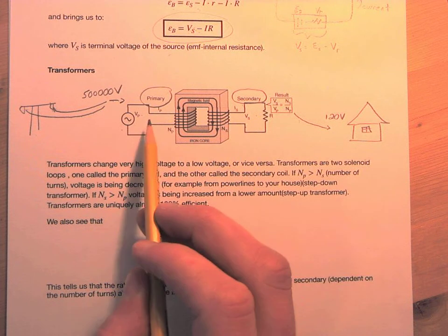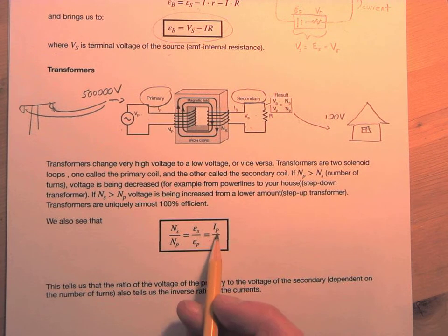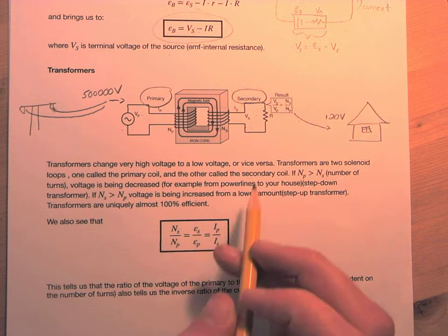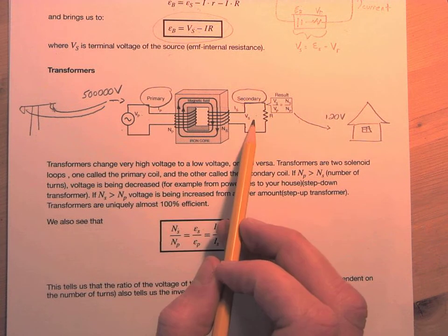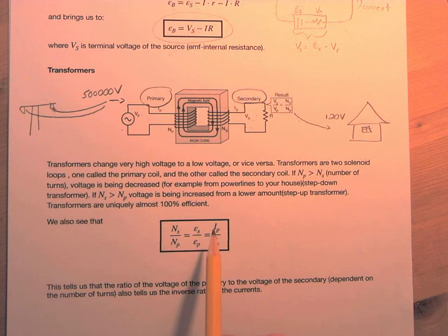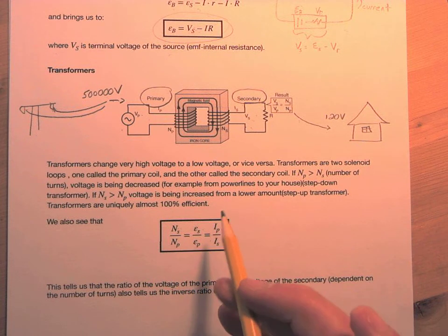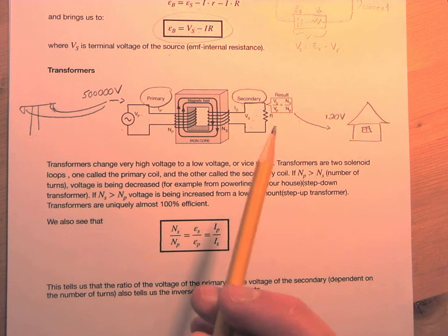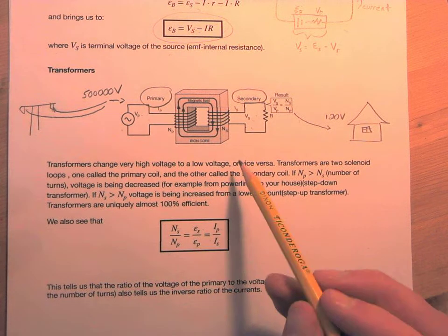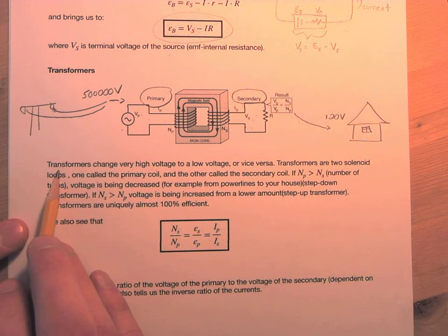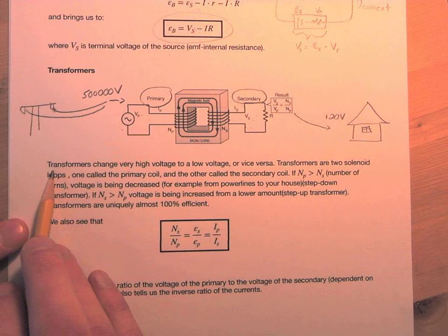Okay? But if you drop the voltage, you can see the P and the S are switched here versus S over P, S over P. This is P over S. If you drop the voltage down, that essentially increases the current that you have. Okay? So it increases the current if you drop the voltage. Okay? And that's another thing to worry about, because really high currents is what creates heat and essentially can create fires. So let's go through this really quickly.